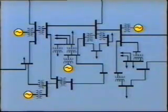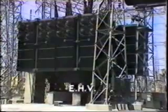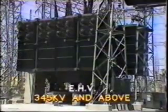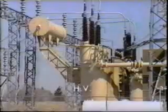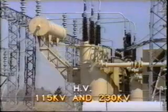As a general rule, most utilities find that they can adequately monitor the system by installing recording machines at every station in the extra high voltage range, that is 345 kV and above, and every other station in the high voltage range, such as 115 kV and 230 kV.